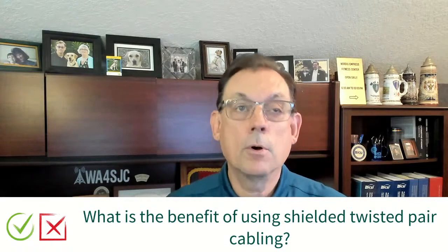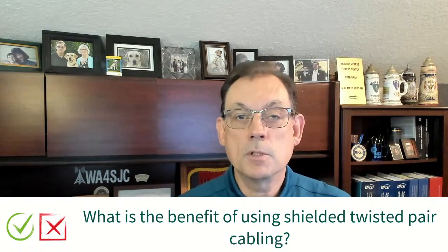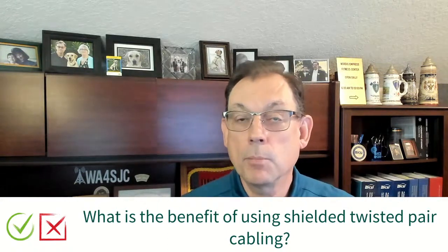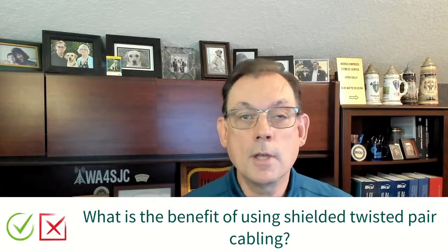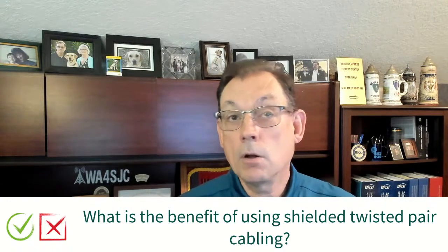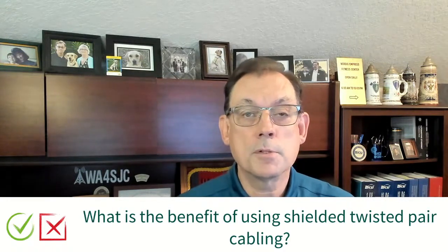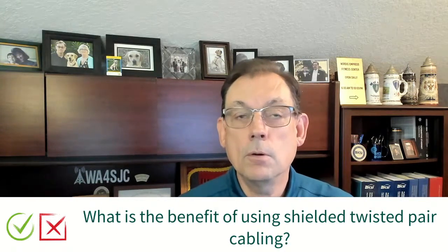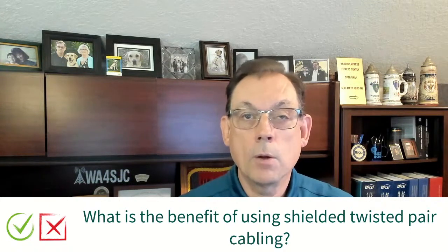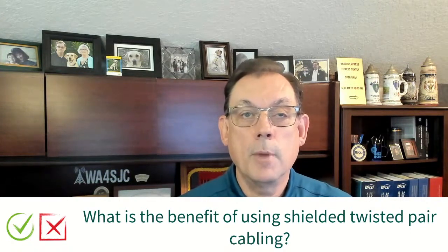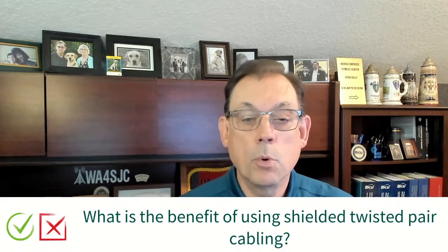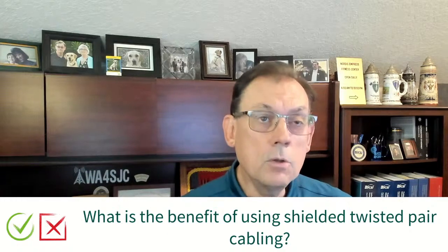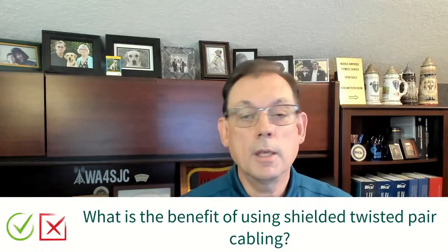It's annoying on a phone call, but for high-speed data transmission, especially when we start getting up into the multi-gigabit speeds, it becomes a big problem. That's one of the certification tests that we do, and our qualification plus tester, the network service assistant, also does crosstalk testing. Crosstalk is one of the big tests when we're certifying or otherwise testing cables, to make sure they're ready and will support what you're going to be running over them. So by adding that shield, you decrease the chances of noise getting in or getting out.